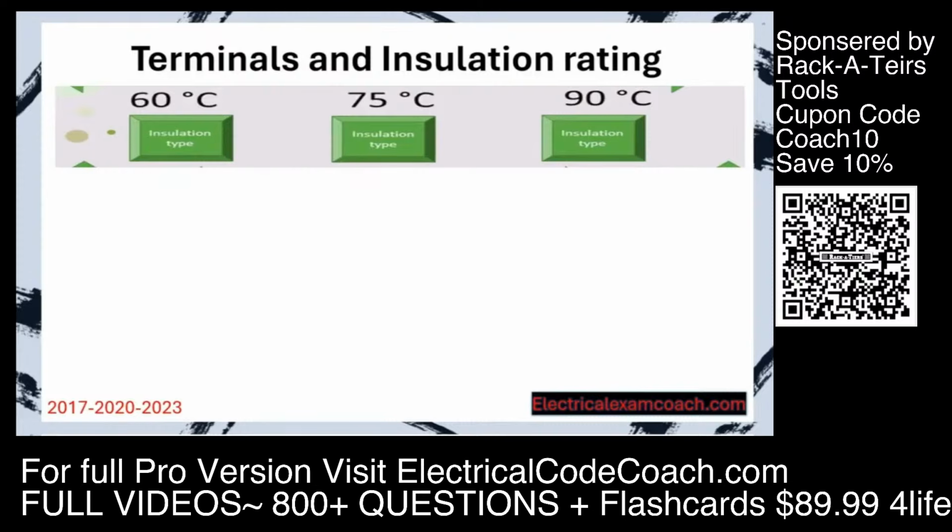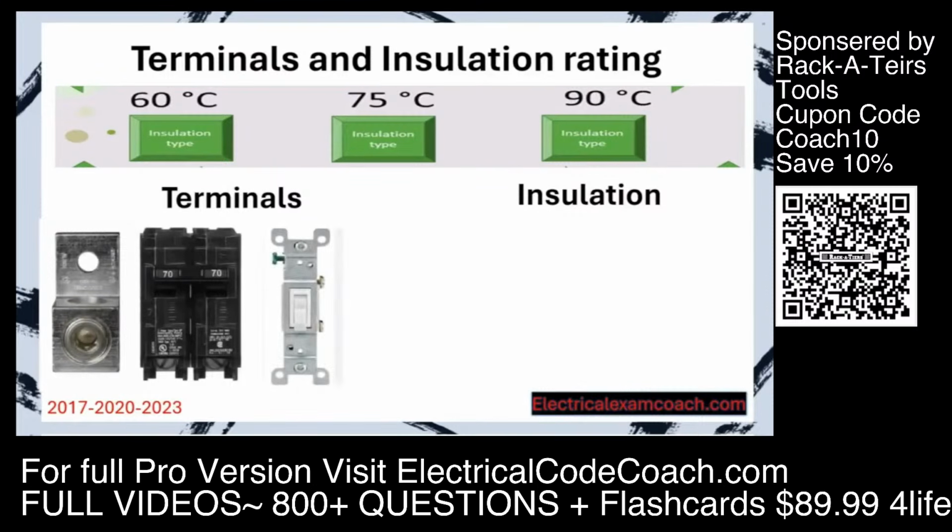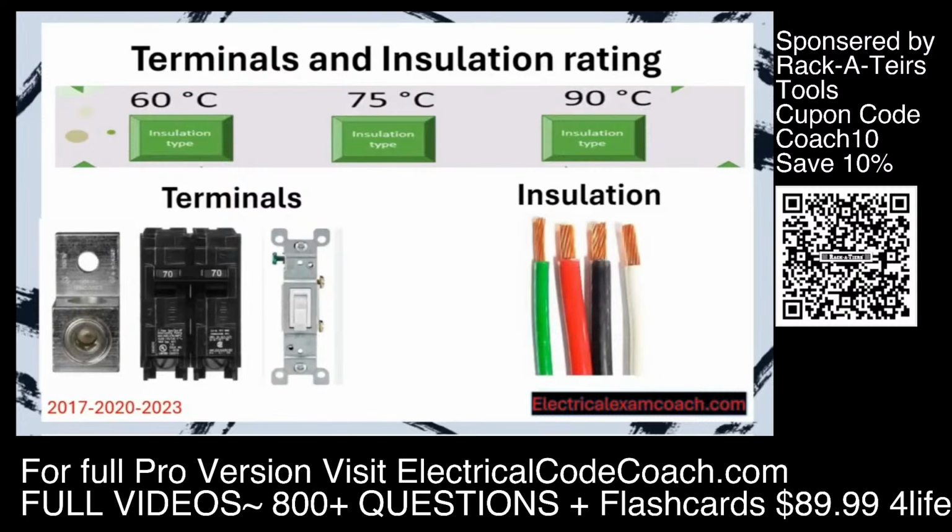And that's where these 60, 75, and 90 degree C columns come into play. Whether we're dealing with terminals or insulation around the wire, each one of them can only handle so much heat safely. Whether it's a lug or a breaker or a switch or the insulation around the wire, they're all rated for specific temperatures. I'll give you a little heads up. Out in the field, all of these are almost 99% of the time rated for 75 degrees C.